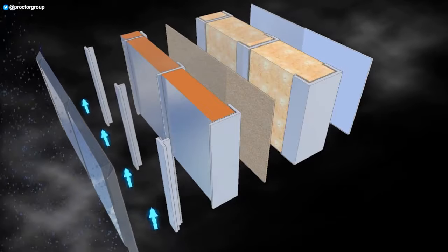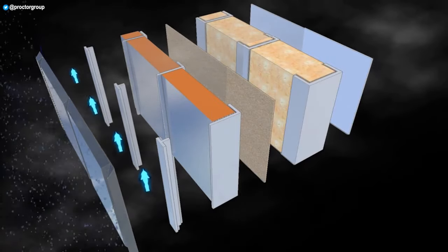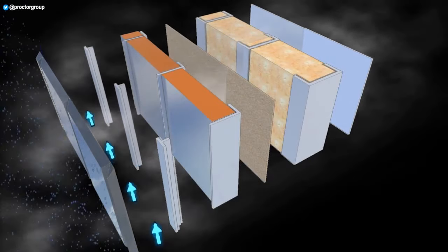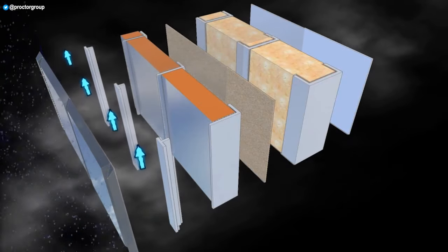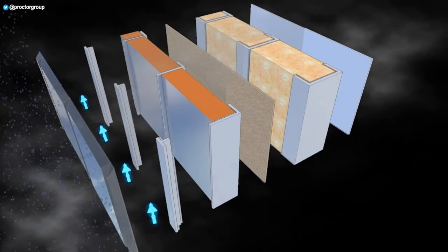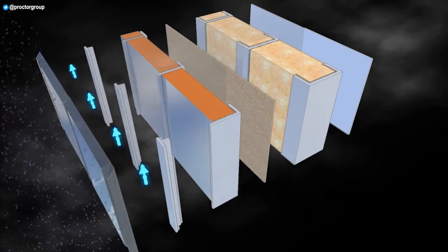However, it does also mean that achieving a good airtight seal of the inner leaf is critical to minimise air leakage. A well-designed weather-tight layer is only as good as its durability, and a carefully designed rain screen that cannot resist damage will be limited in its usefulness.